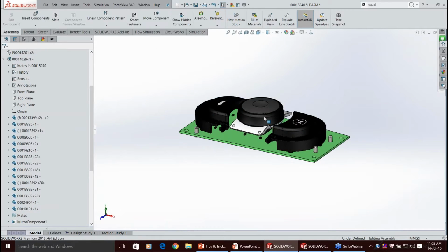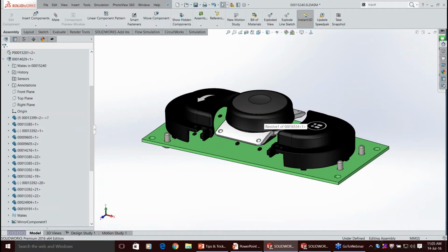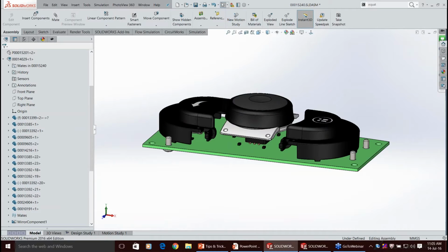There's an option to quick hide your parts or assemblies. And then by pressing the G key, we get something called the magnifier. One of the advantages of the magnifier is, as I said, if you don't want to change the orientation of your part or assembly, but you still want to give some mates, or you want to have a section view, you can just use this magnifier.